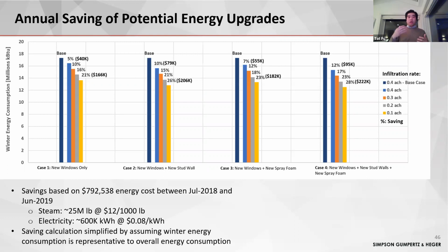And if you're also going to do an upgrade on the wall, your walls also leak air as well. And if you're upgrading the wall and you're putting in more insulation, the more barrier you sandwich between the wall, generally speaking, the more air leakage improvement you can get as well. And these are actually measured.